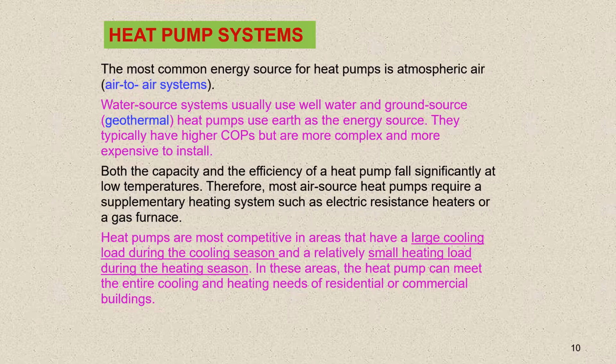The coils can be defrosted, however, by reversing the heat pump cycle, running it as an air conditioner. This results in a reduction in the efficiency of the system.